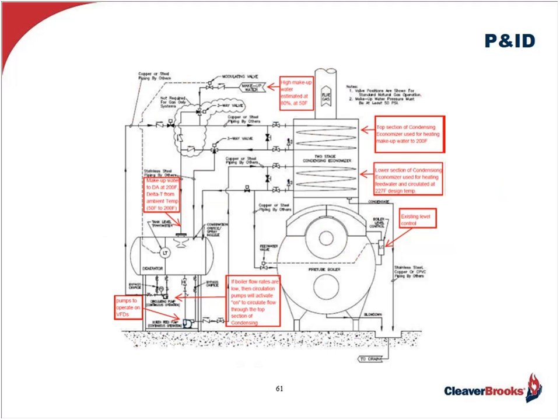There was also, in this particular case, an excellent opportunity to save considerable energy through the use of a dual economizer, wherein there were two sections. One non-condensing section for further heating deaerated feed water, and because they had a need for cold water heating, a condensing section was put on top for this purpose. So the condensing section is now grabbing the latent energy from the exhaust gas after it's gone through the non-condensing section, lowering the stack temperature to below the dew point, adding significantly to the fuel savings.